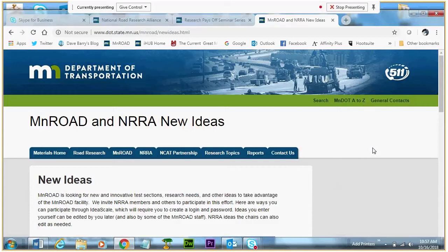Even when we did this for the RAB material that was published, we always try to do a sensitivity analysis: what if, let's assume that you are including RAB in your design, just for the sake of explanation here. If you are including RAB and your pavement design life is decreased by 1 or 2 years, are you still okay? So these sensitivity analyses are very important. So we do that, yes.